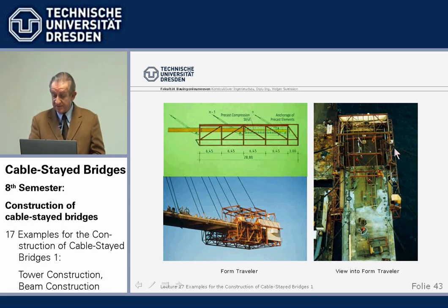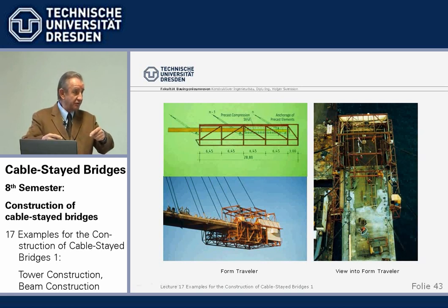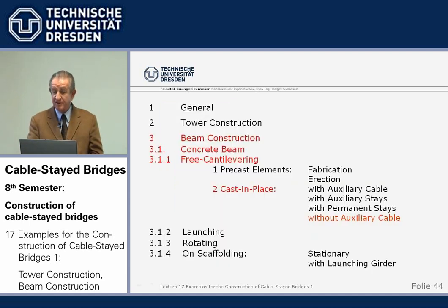But in this case, these cables which support the carriage here, at a 12-meter distance, a length of 12 meters, are the final cables. So no elongation of the cables as with auxiliary cables, and restressing we need, but replacement and all that. So that is a fairly simple method. It took us some bridges to arrive at it, but I think it's okay. Well, you can't beat not using any auxiliary support, be it final, be it permanent.